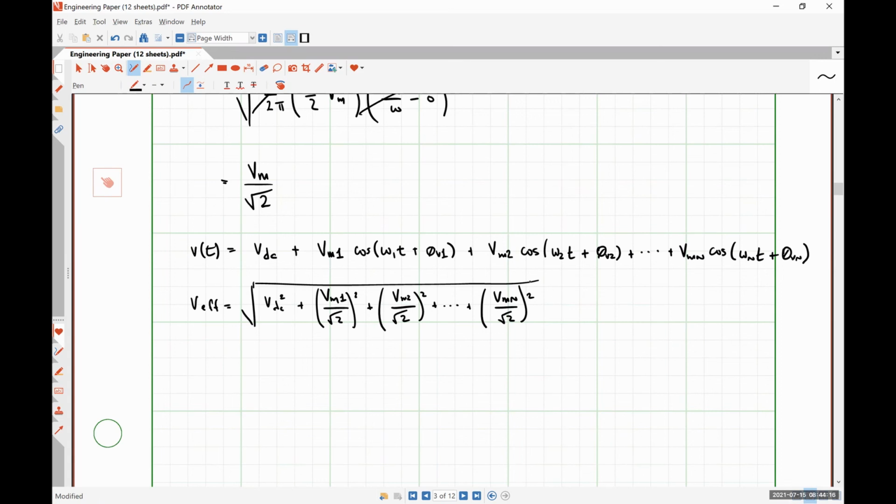Now the reason why this is so important is because if we're dealing with a multi-frequency circuit, we are using superposition inherently. Power is not a linear quantity because it depends on the voltage squared or the current squared, which means we cannot calculate power using superposition. We would literally have to fall back on that monstrous looking instantaneous equation and then sum all the DC parts together. This is a workaround to having to go through all of that trouble.